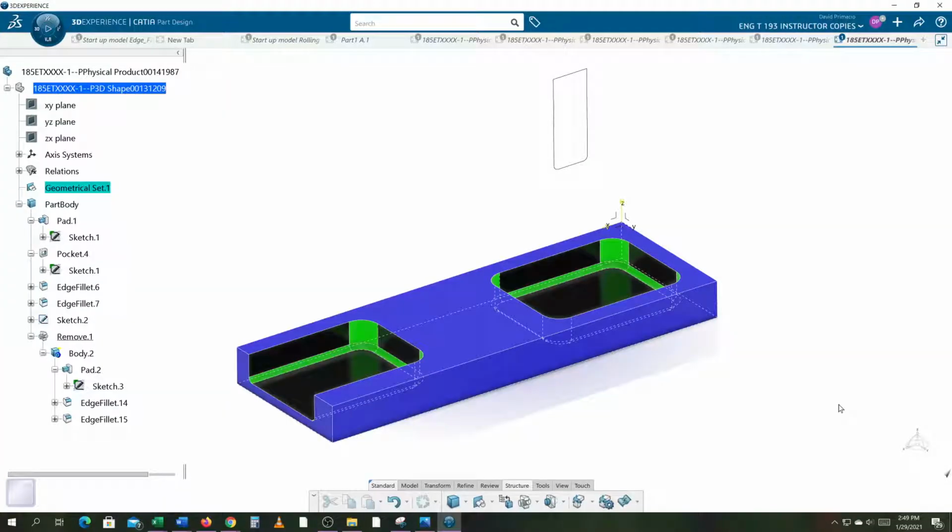Alright, let's talk about the cutter and why this really doesn't work out so great. This is a 1-inch end mill with 1/2-inch radius on the bottom, which means this cutter is going to come down and cut into here, and this radius on that face is the same exact size as the radius of the cutter. And it's going to come around here, so in theory you would get a nice perfect 1/2-inch radius as you make your cuts.